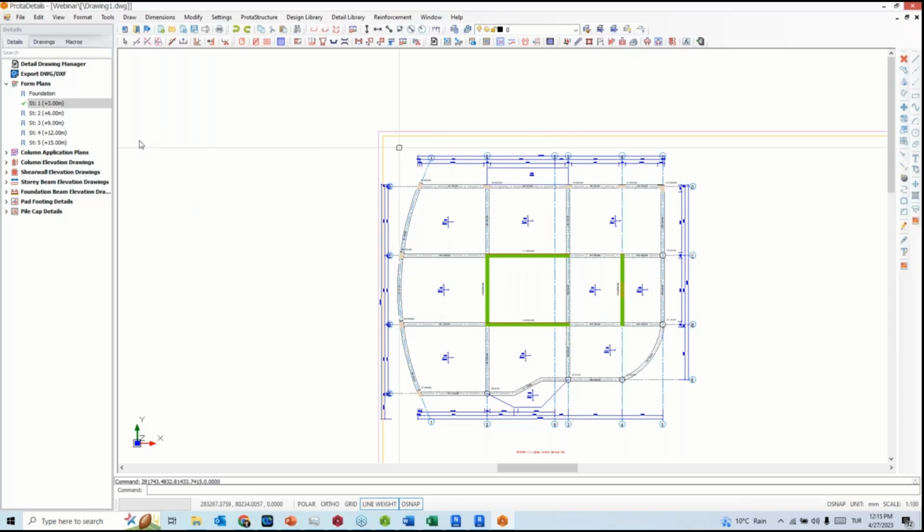Column design software doesn't consider the slab as brace, so the coefficients for the effective length factors are unrealistic. But you can change the members' effective lengths manually. Of course, at some points the software may not detect these effective length values automatically.